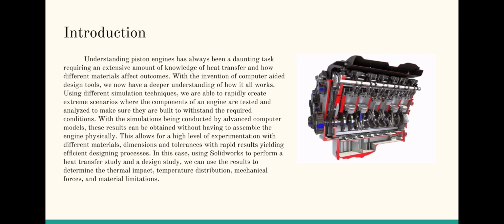With the simulations being conducted by advanced computer models, these results can be obtained without having to assemble the engine physically. This allows for a high level of experimentation with different materials, dimensions, and tolerances, with rapid results yielding efficient designing processes. In this case, using SOLIDWORKS to perform a heat transfer study and a design study, we can use the results to determine the thermal impact, temperature distribution, mechanical forces, and material limitations.